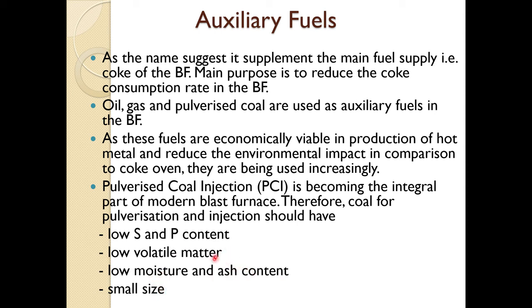So, ash content certainly is always a problem, as we discussed in coke also. Ash will increase the volume of slag and create some other problems. So, ash should be low and moisture should be low. We do not want to use the fuel just to heat up the moisture. And size has to be very small. So, this is a very critical parameter in PCI,